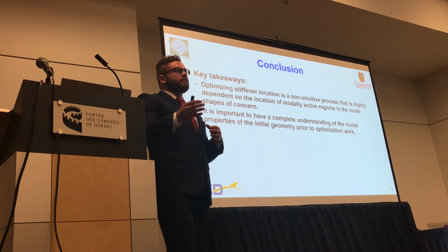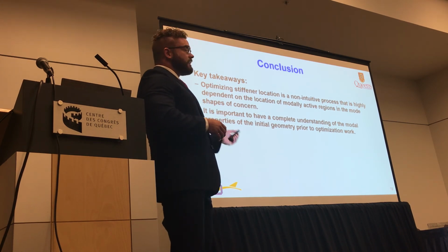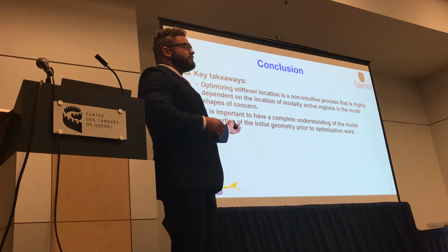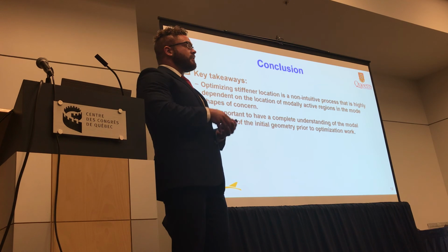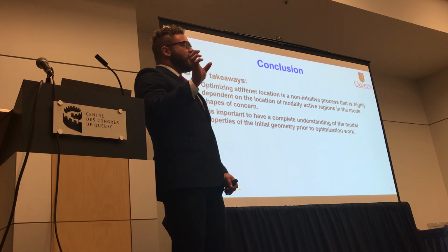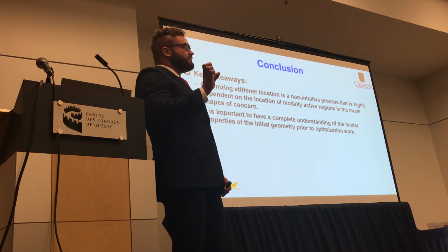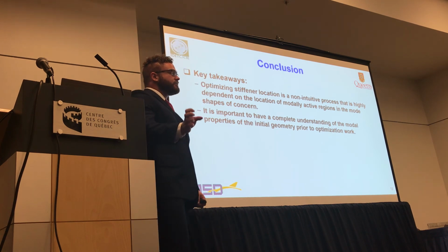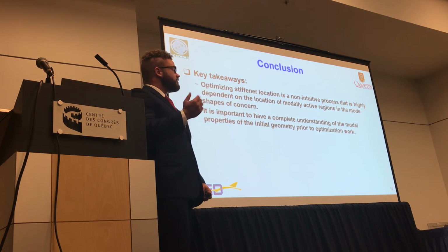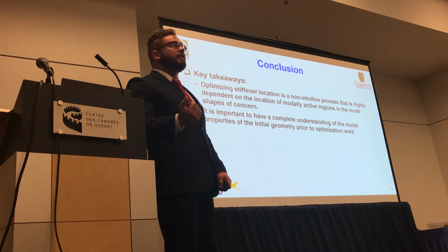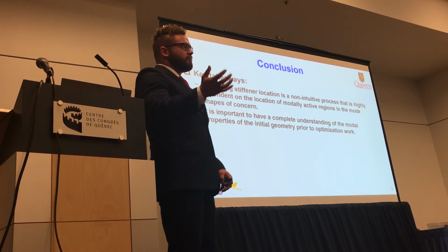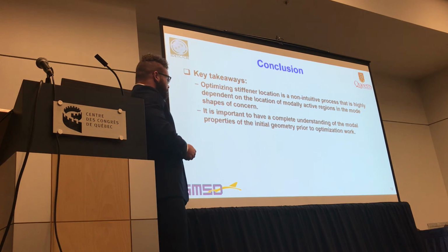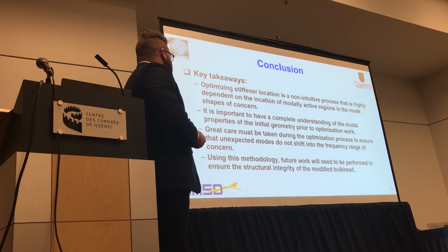But in this case, where the engine excitation frequency is in between several modes, we really need to understand what mode shapes are in that range of concern, because different stiffener configurations will affect those modes in different ways. So we really need to have a fundamental understanding of how those interactions come into play before we start performing more advanced techniques.